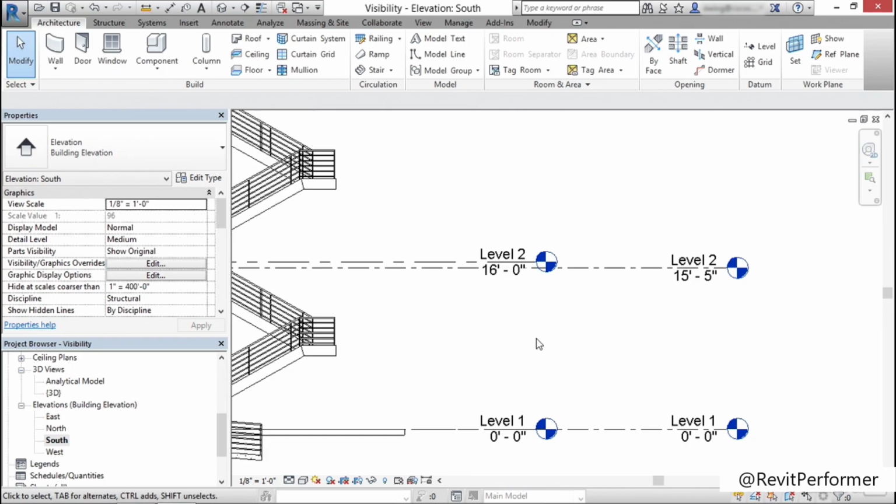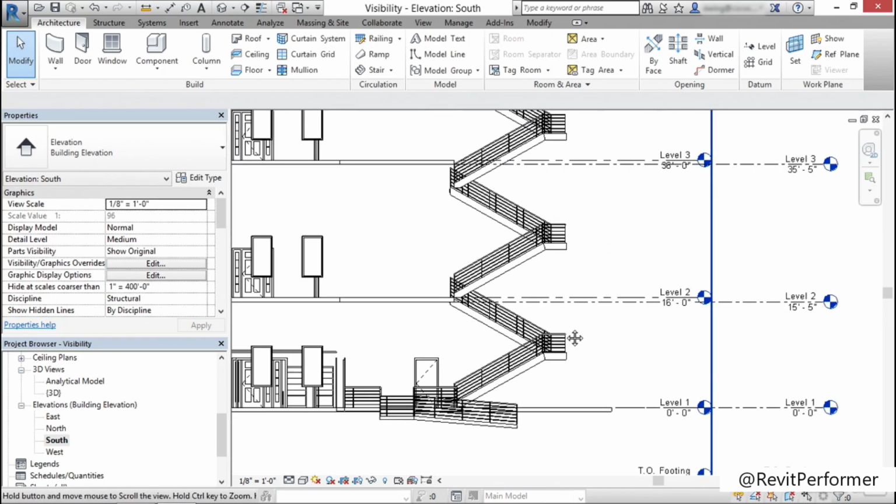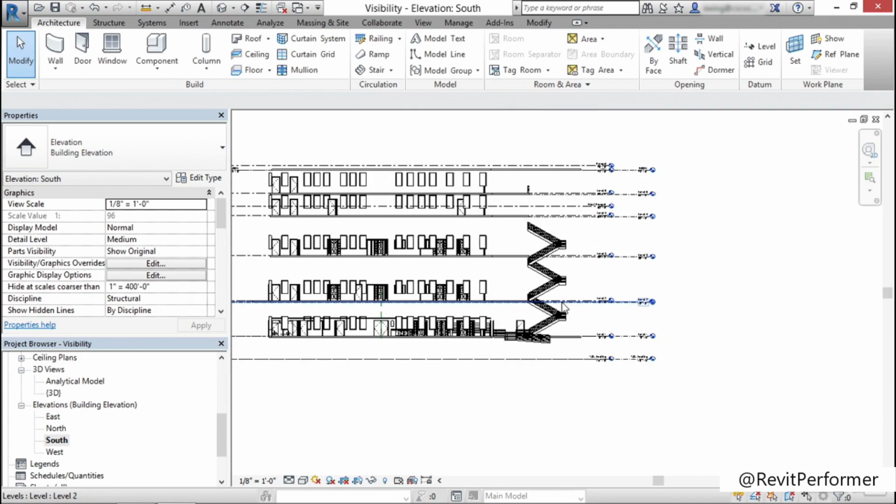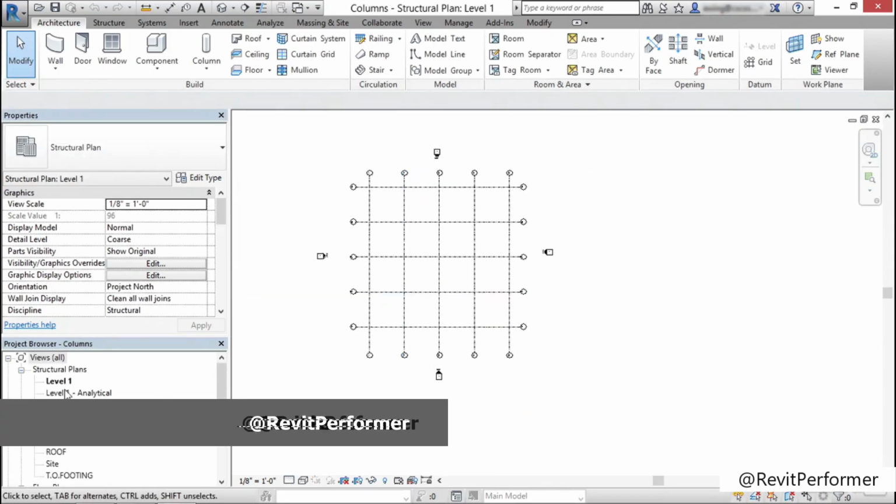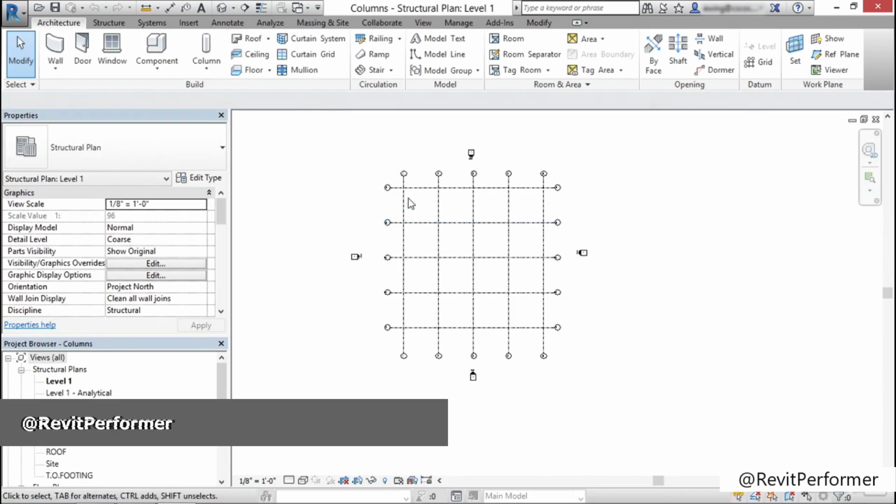The reason I really bring this up is because whenever you open a Revit model and you get a coordination alert, there's nothing wrong with Revit. Your BIM manager set it up that way on purpose. Go to Coordination Review and see what they moved. And notice we have level 1 up to roof. When we put columns in, Revit likes to look downward.